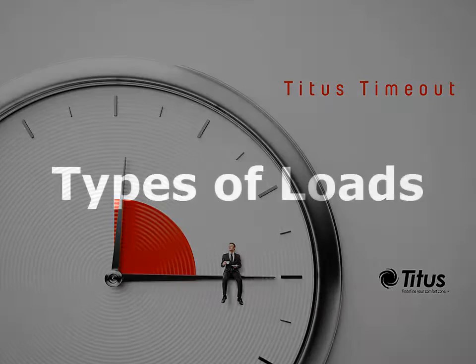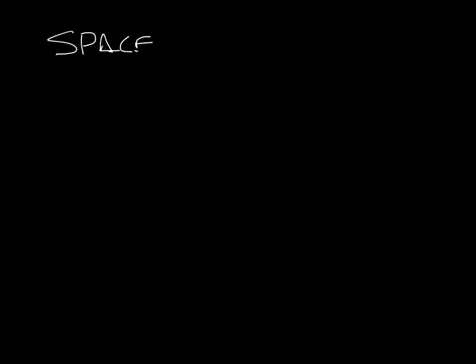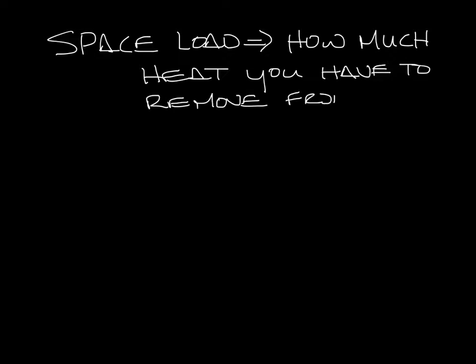I'm Jenny Abney-Civy, and this week I want to talk about the types of loads in a building. The space cooling load is the rate that you have to remove the heat from a space to keep it at your desired conditions. It's basically how much cooling you need to keep it comfortable.